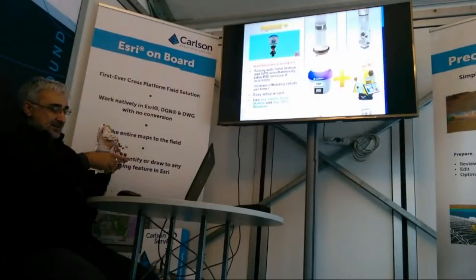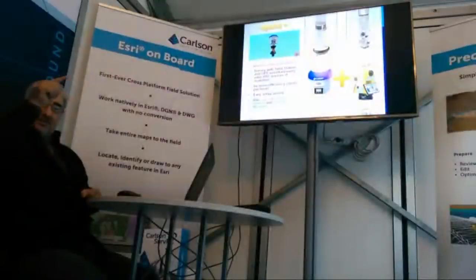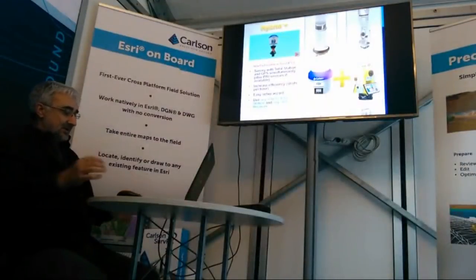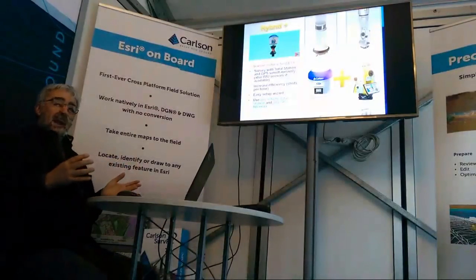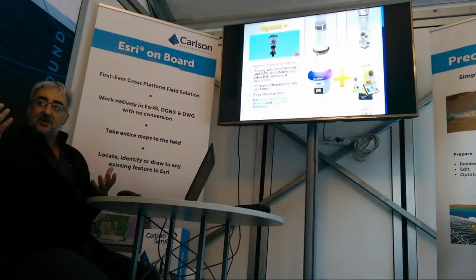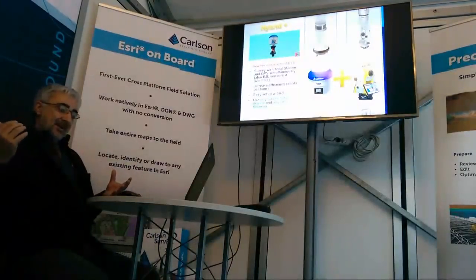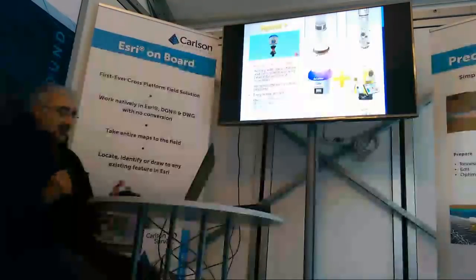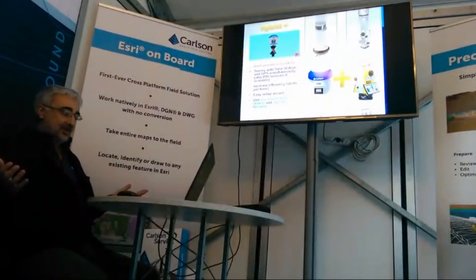GPS with sensors, compensating to the prism and using the sensors of the GPS to compensate. Yes, we do. So we can also increase efficiency. You will see why. Because you can play robotic and non-stop always have position. No matter if you have a prism lost, we automatically use the GPS and automatically search. We see that later. But this is efficiency because normally in a robotic, anytime you have a trouble, you have to stop. You do nothing without the prism.